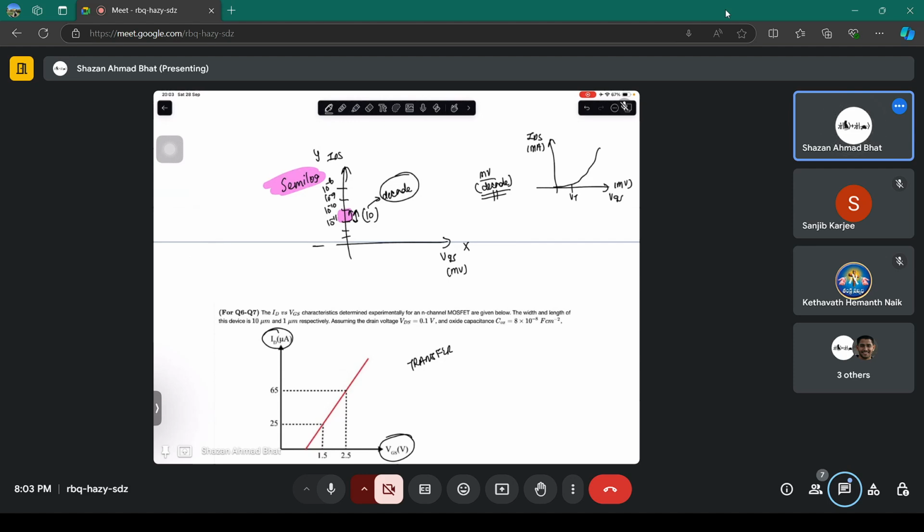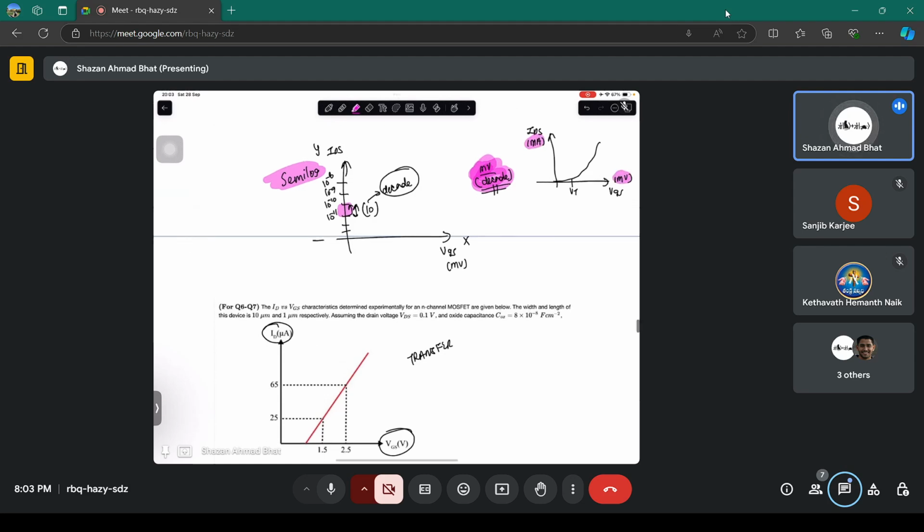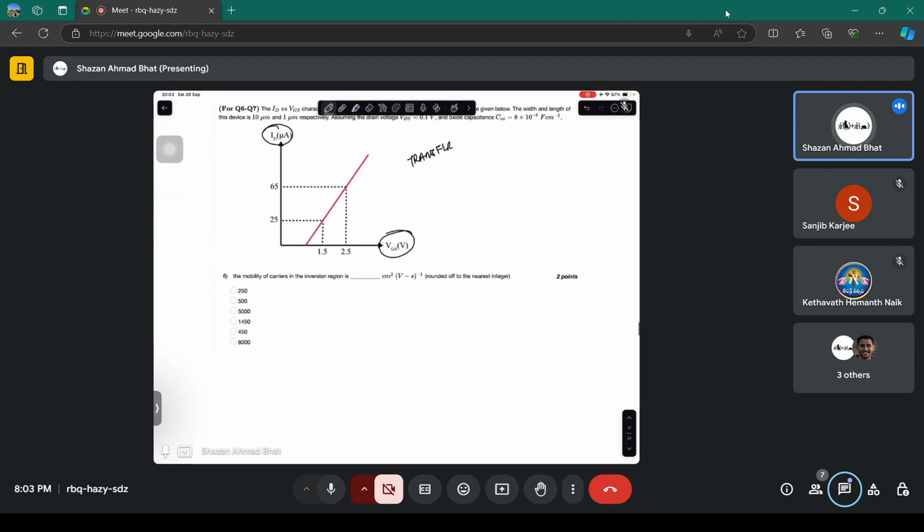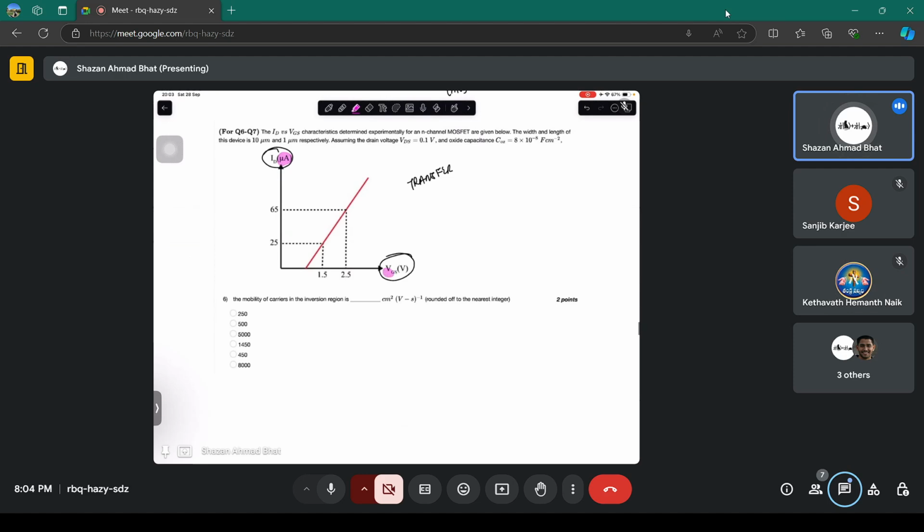The unit millivolt per decade appears only on the log plot. Here it will be linear units, not decades: amps, or whatever is on the y-axis. That's why you see micro amps and volts written here, because this is just a linear plot.